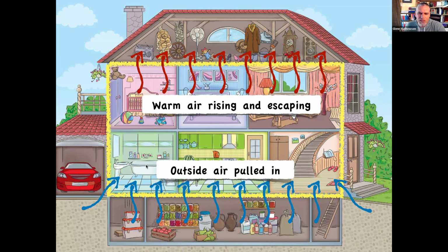And again, this is just an anecdotal photo, but this point still drives home that if you need to retrofit an existing home, like my 1958 house, last summer, I did some work in my attic, and that's where I did the air sealing. Air sealing in your attic space to stop that warm air from rising, you're basically attacking the very first issue.